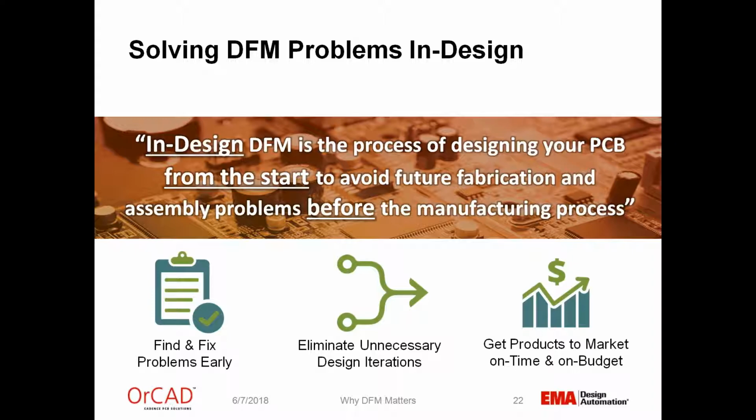All right, good to know. Is this real-time DFM checking functionality an extra cost? Great question. So it's actually part of your core tool. If you have ORCAD Standard or Pro, these core checks are now part of the tool. If you have the latest ISR, you would see the new domain in the Constraint Manager. It was introduced in ISR 38. We're currently at 40. So if you go out and get the update, you'll have the latest DFM stuff.